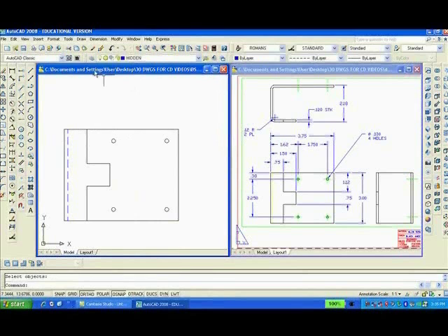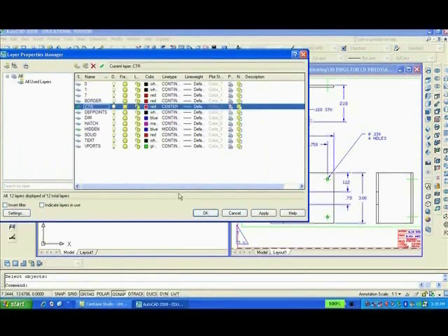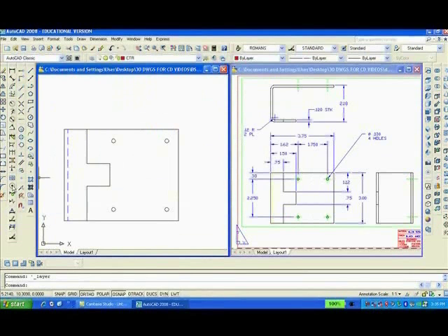We'll go to the layer called center and make it current. And we'll pick a mark, put it right there. It's awful small. Oh, that's all right. We'll do the same for all 4 of them. Because since we're on layer center, we can draw a line connecting. And we can change the linetype scale, LTS, 0.6.